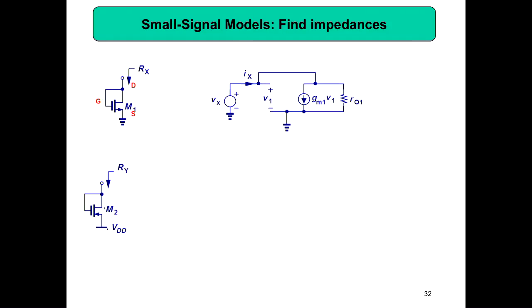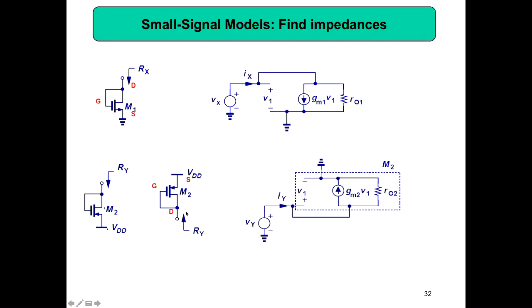Then another one is this circuit. So are they same or different? One is NMOS, another one is definitely PMOS, because you can see the arrow is going in. And then my question is, you can draw the small signal. I drew the small signal. Then what I did is I flipped it down so that it will be kind of looking like this. See, and then I have drawn the small signal for you. When I draw the small signal, I'll be getting something like this.